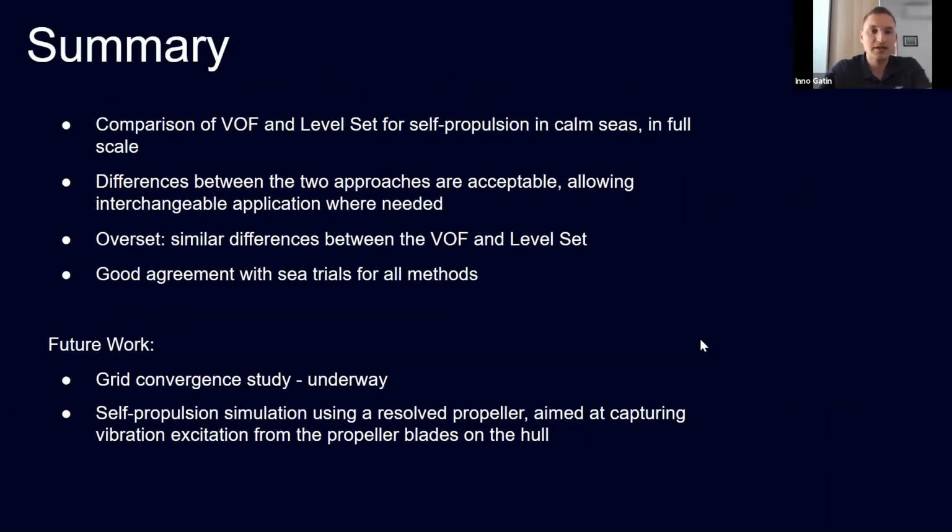So to summarize, what we needed to do and make sure of is that we can use VOF and level set interchangeably in some cases without having to worry about accuracy of the forces being calculated acting on the hull. We have found that the differences are acceptable between the two approaches, and we have found that also with overset the differences do not change considerably. We have seen good agreement with sea trials, however we need to do some more work on that as well.